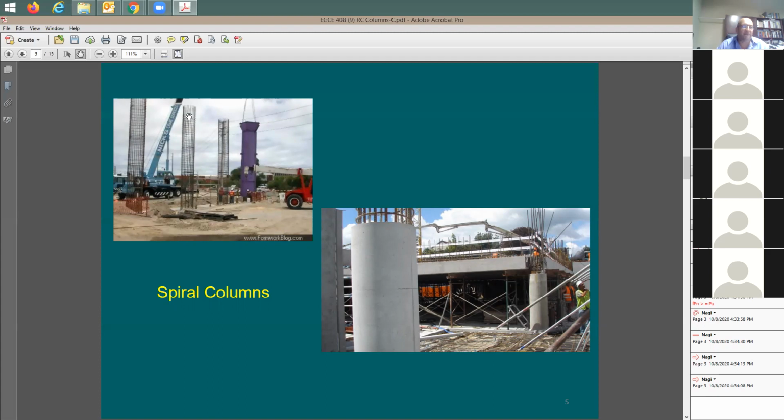You're not going to do it on an office building, but most likely in a parking structure or in a bridge. In most cases, you can just build this on the side, carry it with a big crane, put it in place, put the formwork, and then cast it. And again, you're going to have some dowels stick above, right?